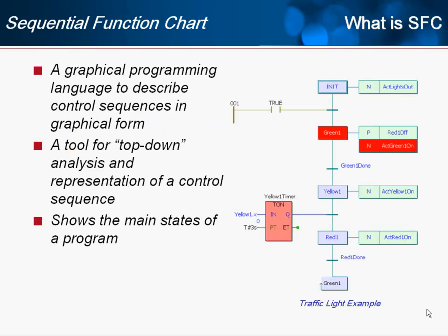So first, what is Sequential Function Chart Programming, or SFC? It is a graphical programming language that lends itself very well to high-level programming of a control sequence. It's basically a flowchart that contains different parts of the program and controls the top-level logic of your program. And so using SFC, the steps of an automated process can be very clearly and simply represented in the program itself. And I think an example best illustrates this.